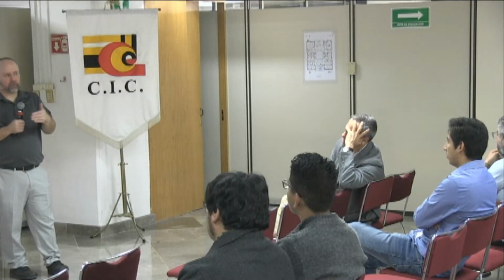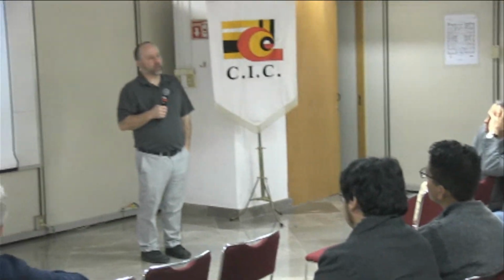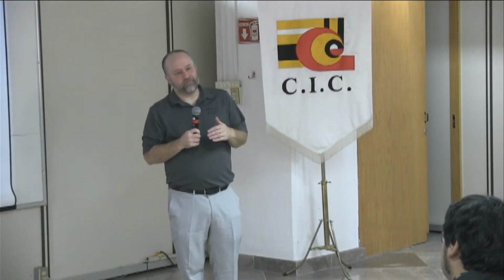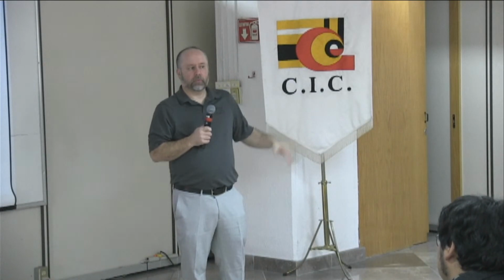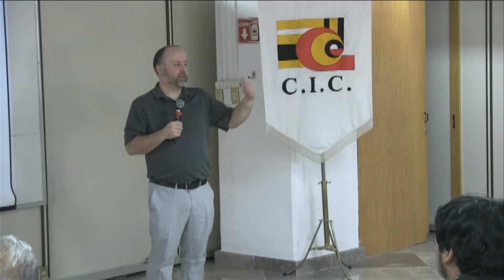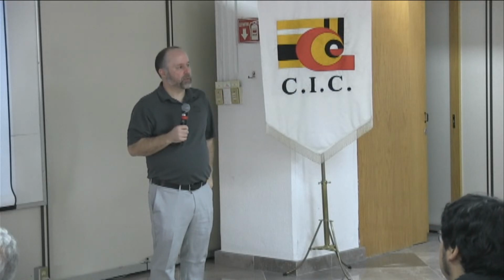So, good question. For RTL type stuff, a lot of the basics are very similar, but for Micron, we do very little RTL. A DRAM by nature is almost a giant analog block. It has asynchronous clocks. The entire memory array is analog. It has large analog blocks. So the vast majority of our design is traditional, full custom, starts with schematics, direct layout. Now we still have standard cells. Things are still built in automated fashions, but there's only small portions that are built with RTL.